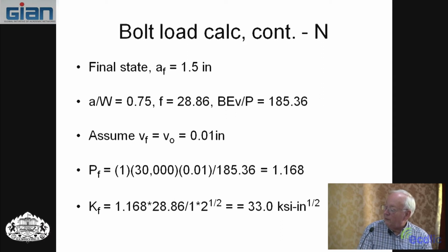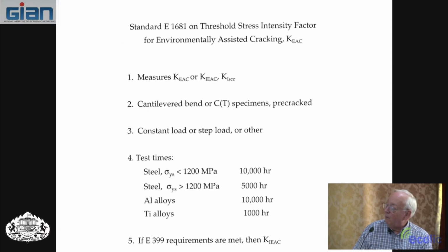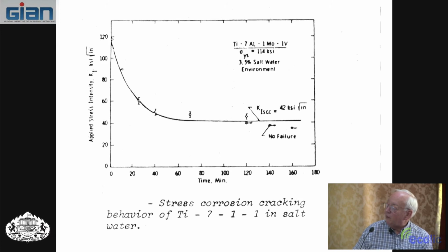So the K did drop significantly, and the idea here is if you have a threshold and put it in the chamber, the crack will keep growing until you hit the threshold. So go way back to this, actually you're coming from up here down there, and you're hoping that once you hit that, the crack stops growing.